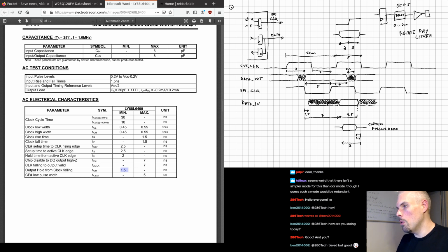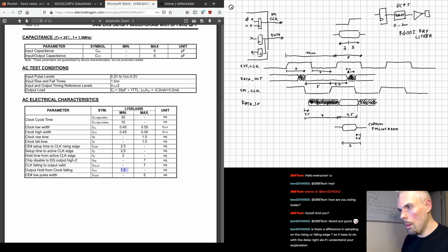And it has latency. And the problem is one of the bits that the FX2 feeds back is a bit that says if the FIFO is full or not. And that's kind of a problem if you have a 3-cycle latency, right? Because you only find out if the FIFO has become full 2 cycles too late, basically. And so that was kind of a big problem that needed to be solved. You can look at the details and the timing analysis in the issue on GitHub. But yeah, sometimes latency is definitely an issue.